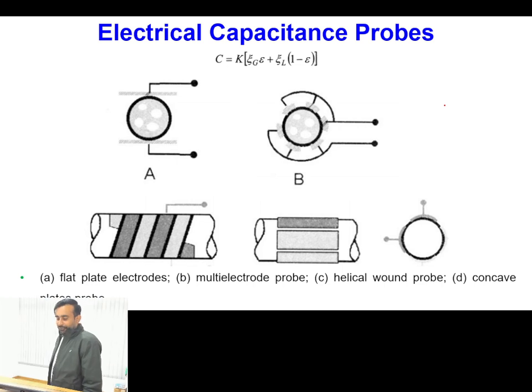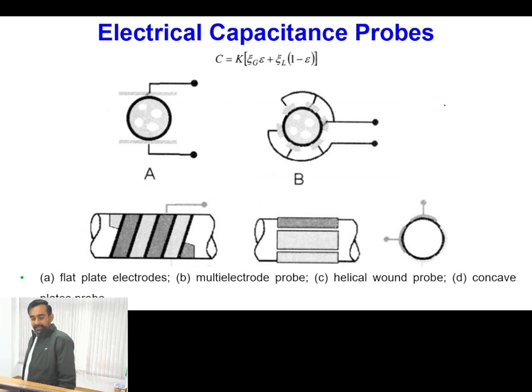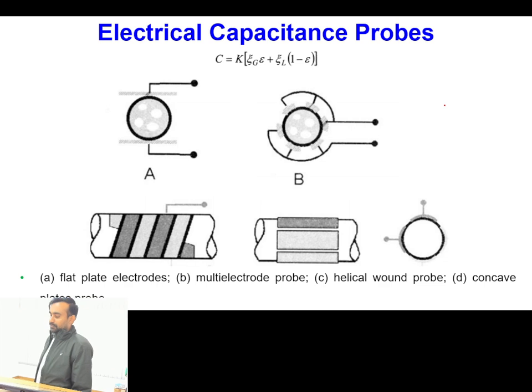And in terms of different measurement techniques, we have already talked about the radiation attenuation based techniques, and then we have talked about optical techniques for measurement of phase distribution function. After that, we discussed the resistance impedance based methods as well as only impedance based methods. And in case of impedance based methods, we were able to directly get the value of void fraction as output depending upon the measured resistance.